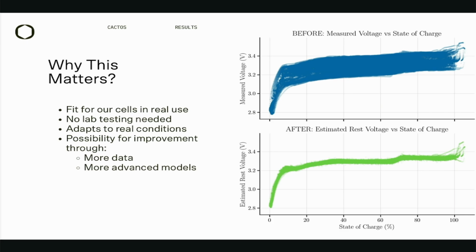And a second question, am I getting it correctly that your model does not depend on battery chemistry? It does depend on the battery it was trained on. For example, these curves change a lot with battery chemistry, and LFP cells are extremely difficult in that the curve is very flat around the middle section. So estimating the SOC from voltage is very difficult. In different chemistries, it can be a lot easier. So it will work, but will give less precision. And if you use the same chemistry, you can just change some parameters and it should work.